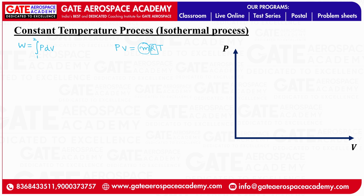For example, let's say air is given or nitrogen is given, right? For a given gas, R will be constant, the characteristic gas constant will be constant. And we are dealing with constant temperature process, so T is also constant, right? So this entire thing is constant, right? So we can write PV is equal to constant. We can write this, correct? PV is equal to constant. From here we can write P1 V1 is equal to P2 V2, right?